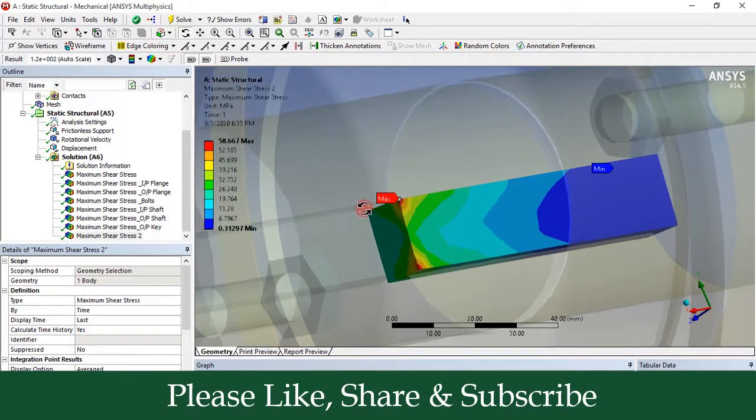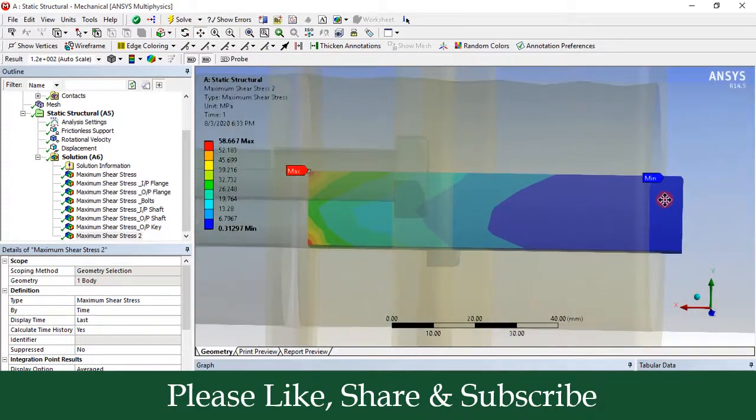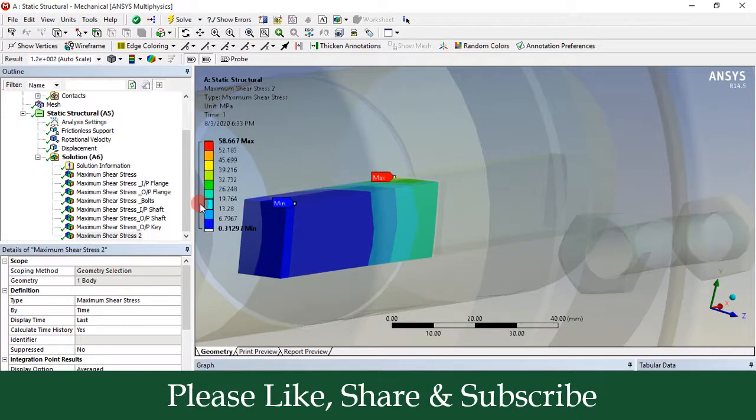So for this input key, the maximum shear stress is present at these two corners of key, and it is minimum in this region of key where there is a blue color. So this blue color indicates the region of minimum shear stress.